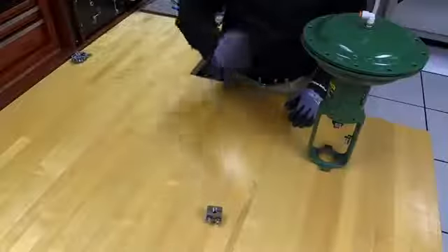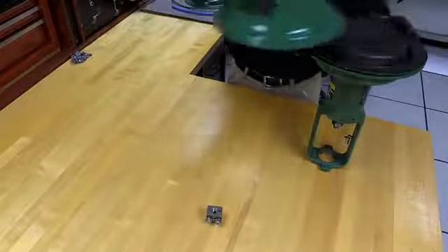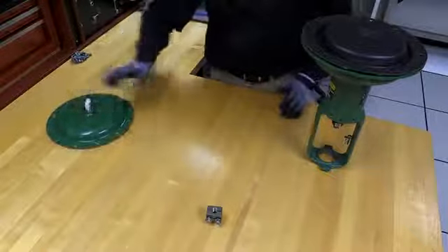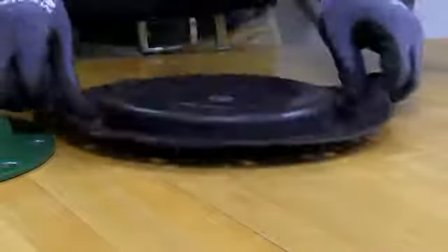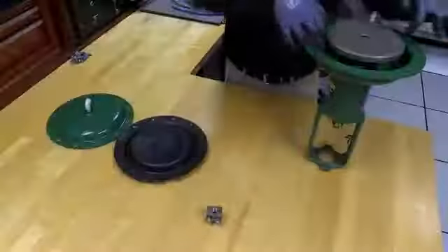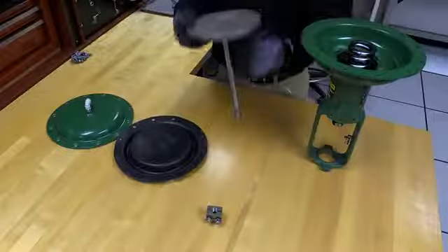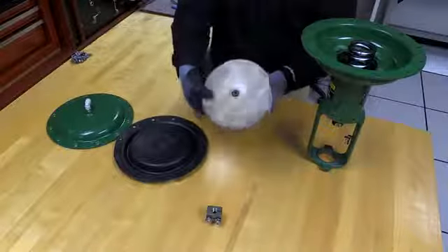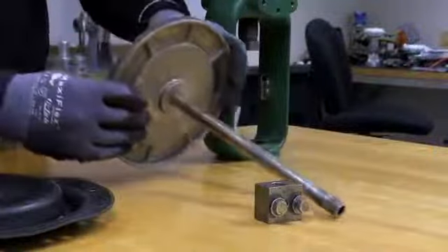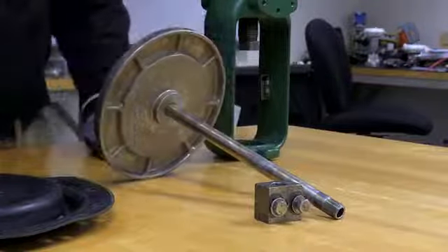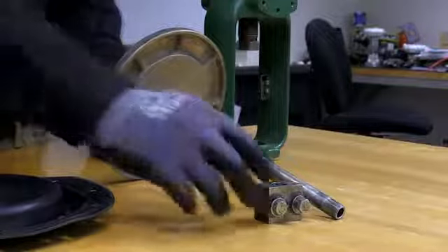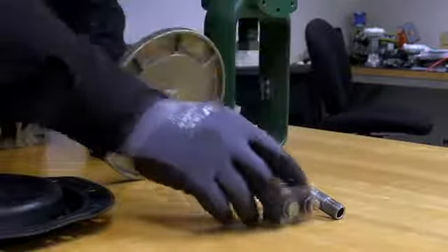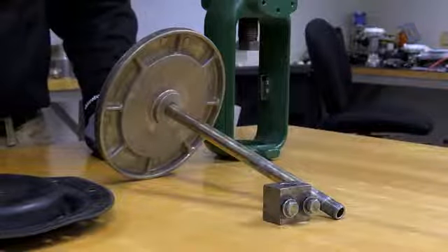The upper diaphragm casing is removed to access the internal components. The diaphragm is a flexible, pressure-responsive element that the pneumatic control signal is applied to. The diaphragm plate is a rigid plate that the diaphragm pushes against as pressure is increased. The actuator stem is connected directly to the diaphragm plate. A coupling block is typically used to couple the actuator stem and the valve stem.